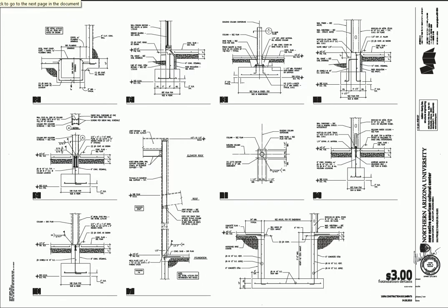Now we're starting to get into the details, and typically structural drawings are organized in series, like 100s, 200s, 300s, etc. So here we can see the 300 series of the foundation details. That keeps the foundation contractor organized in one spot. So I'm looking closely here, and as I start to page through here, I look and see that we have